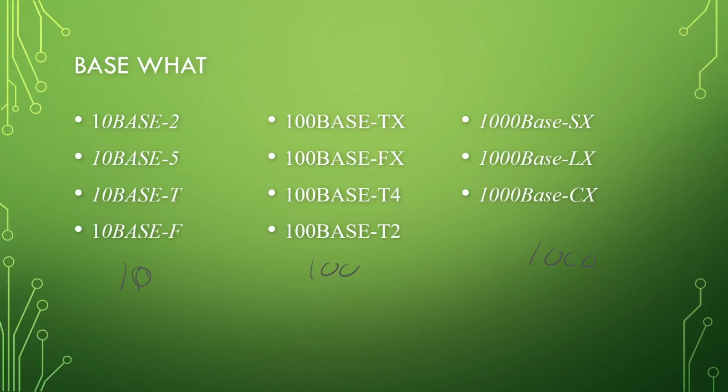All right, well, anyway, for industrial Ethernet, for those standards, the 10 is 10 megabit, the 100 is 100 meg, the 1000 is 1000 meg. Base stands for baseband. If you remember, we had baseband and broadband, so we had those two slight differences. And then the 2 here is defining overall our cable type, our communications system. In this case, it's thin wire coax.